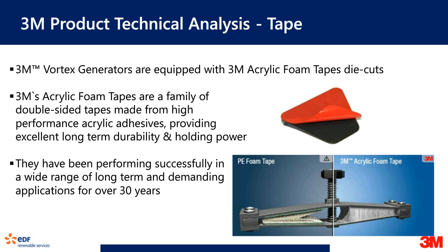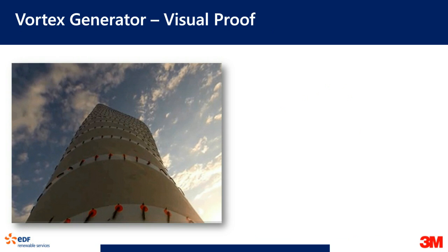So this one slide or one picture comparison shows a very good understanding of what we are doing in just a few pictures here. Now on the left-hand side, you can see a wind blade. It's actually operational. And you can see these flow tufts that we were talking about a little bit earlier and understanding how the flow is happening, where the separation is taking place, and so forth. If you pay attention to the leading edge, the wind flow tuft is basically a bunch of threads joined together, if you may, aligned to the wind direction or perpendicular to the blade length.